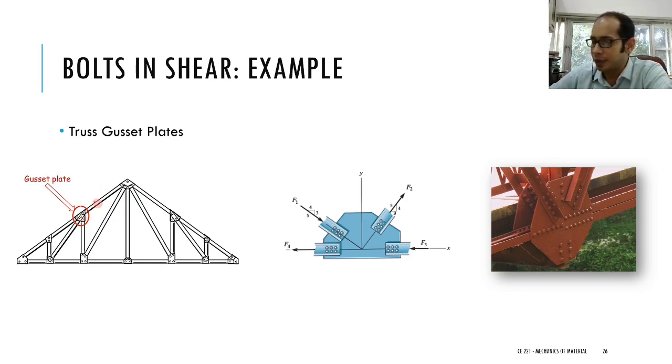In the pin joints over here, if you take a look into the zoomed in view of any of these joints, and if you look at a practical life example, you see these smaller blocks that are there. Let me maybe change the color of my pen so that you can see it better. So these ones, right? These are the bolts that you see. So all the bolts that you see over here, they are actually undergoing shear stresses, because if you think about it, this member is actually pulling into the bottom member, and these bolts are actually undergoing shear stresses.